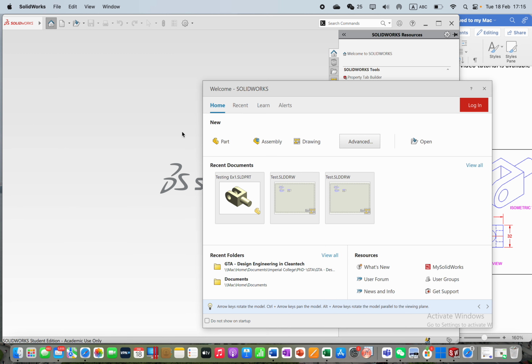First thing we need to do is pay attention to the type of system you are using. For example, if you go to drawing, it is only the 2D version. So if you start with a 2D drawing and then you want to move to a 3D version, this will not work out. So you need to be very careful. If you really want to start by developing a 3D version, use the part and focus only on developing your full system on this. But starting now with the drawing, with a simple 2D design of this exercise I have here.